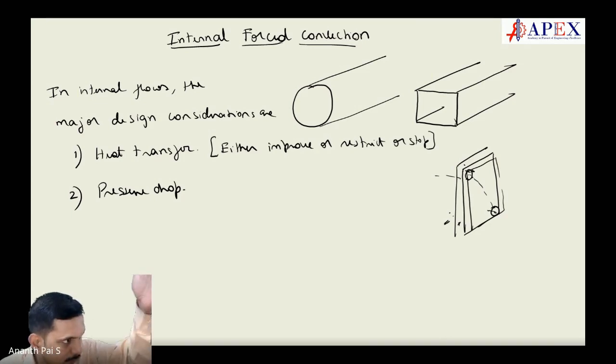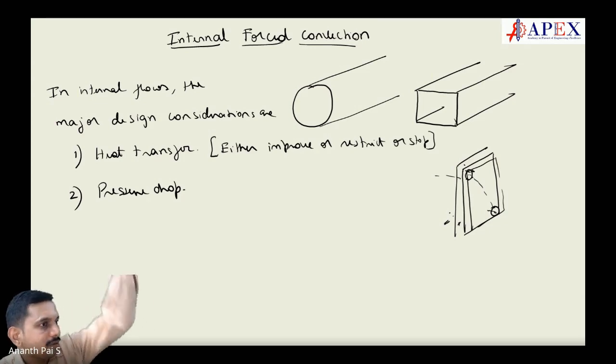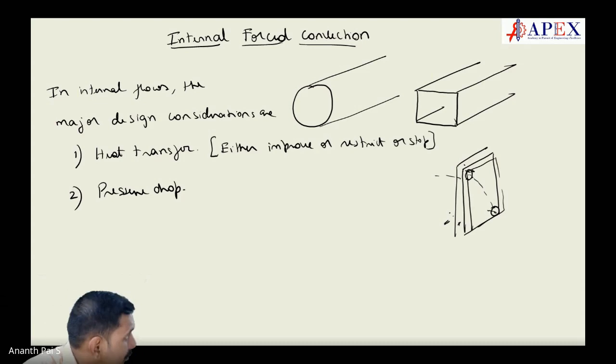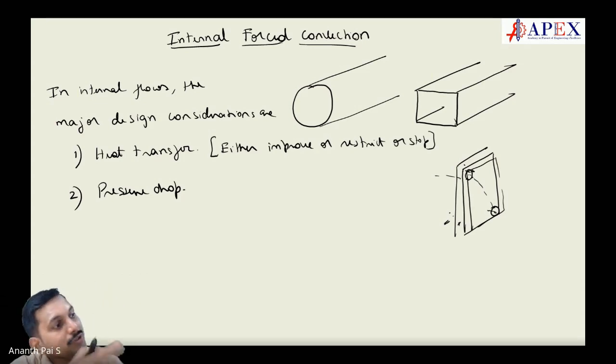So one is the heating fluid, one is the cooling fluid. The cooling fluid can be vapors. The heating fluid goes to one slot like this, skips one, and then goes to the next. In between, the other one goes alternately. These are all called compact heat exchangers. You have high surface area for very small volumes. But these are also internal flows. Keep in mind, these are not external flows.